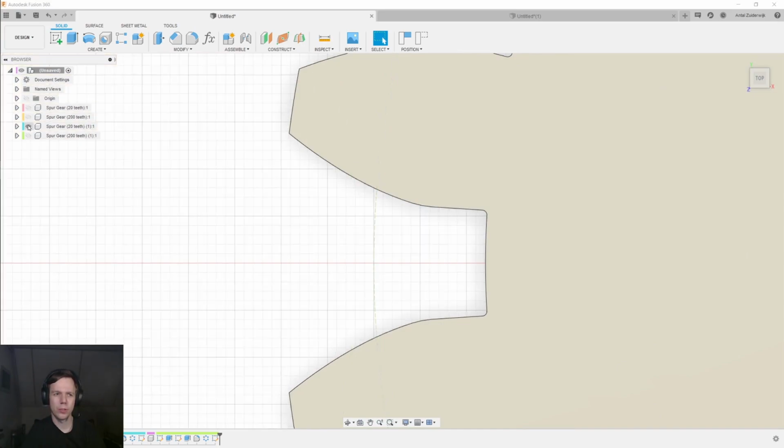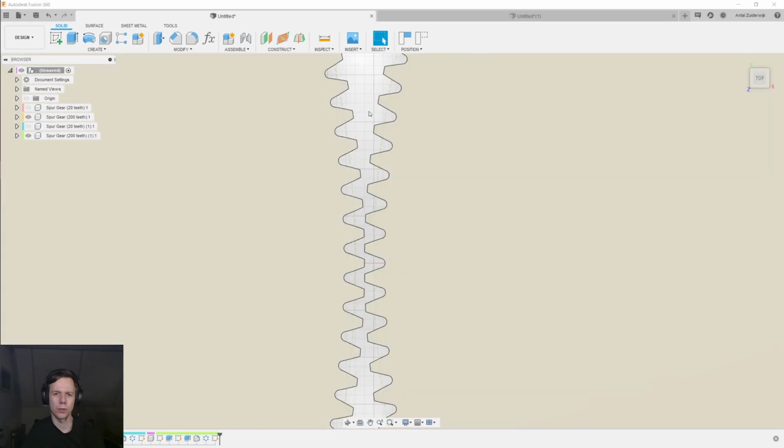But if we now change our view to the module 1 gears, we see that the teeth no longer mesh at all. And so instead of having a little bit of backlash to deal with, we end up with a set that simply does nothing.